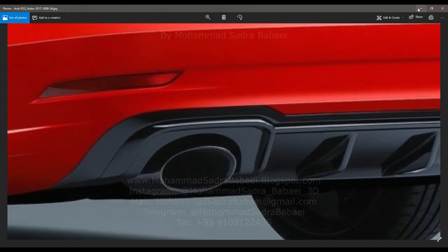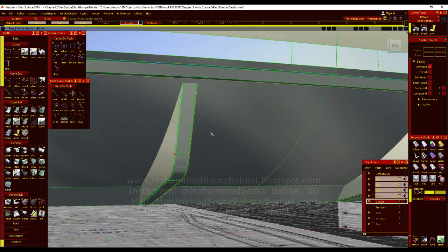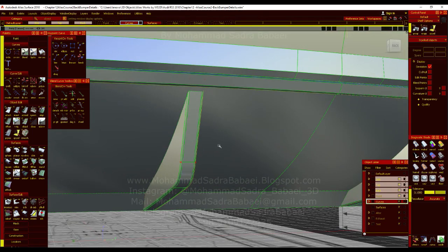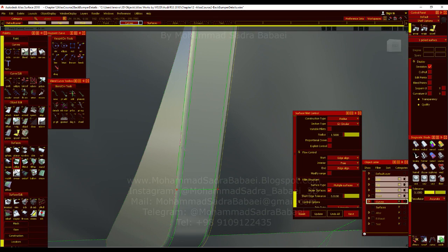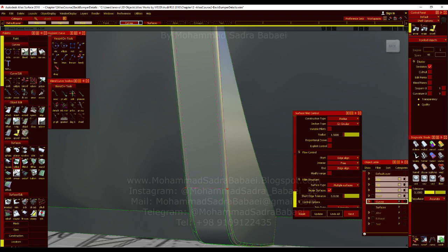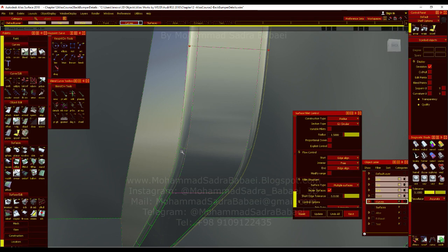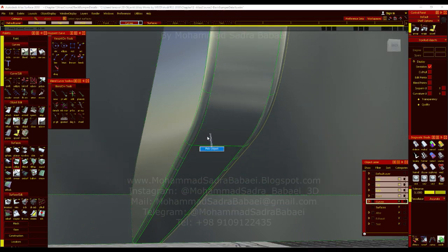And here you can add another fillet. So what is the way? The good way is choosing all these surfaces. As you see, they are all red. It means they are all aligned tangency. So as you see here, we should select all these fillet surfaces because they are Bezier and they are A class.